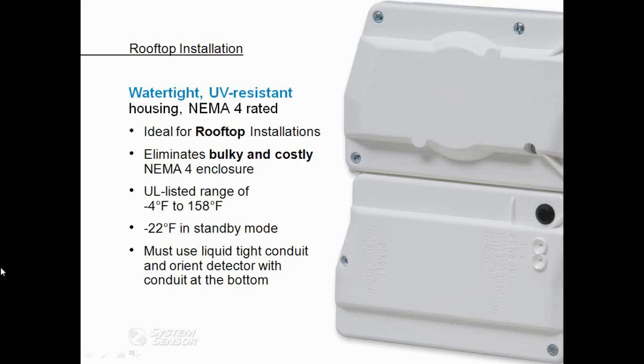When installing a watertight duct smoke detector, it's also important to use outdoor liquid-tight fittings. Those have to be used no matter what when they're installed outside. And then we also recommend that those conduit openings be on the bottom of the detector, just as another safeguard to ensure that water won't get in through those conduit openings.